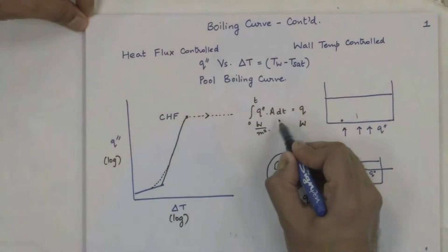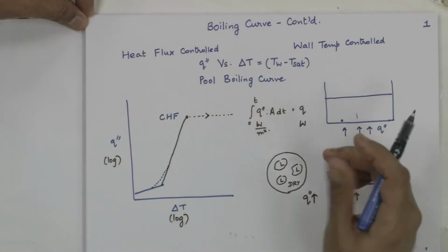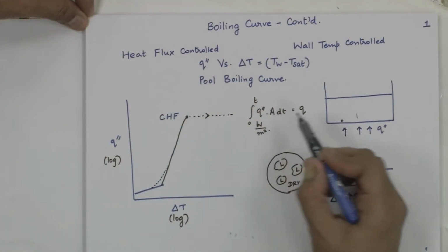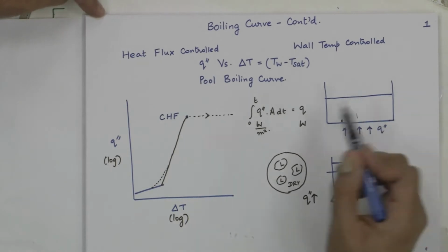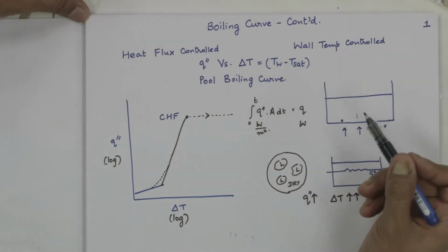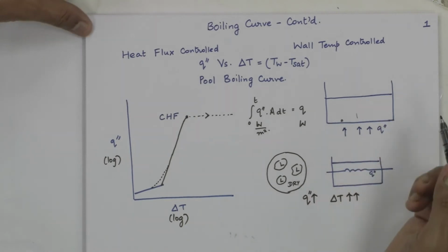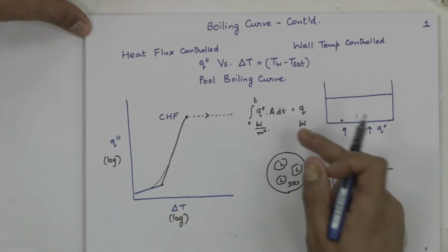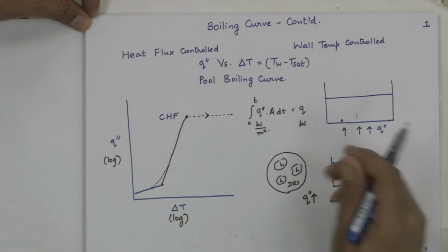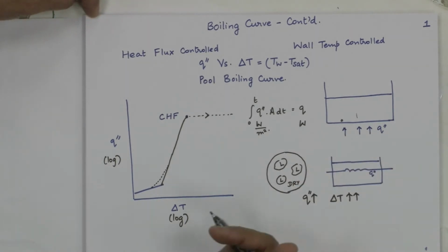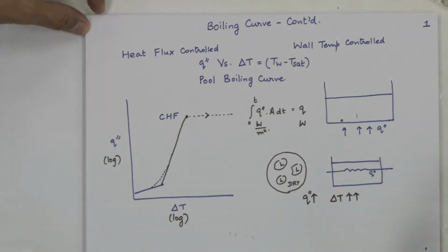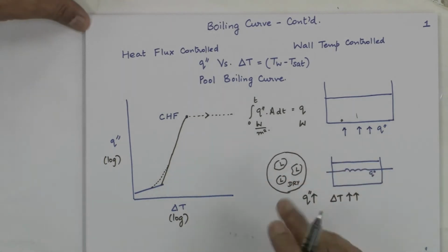This situation could have happened at a lower heat flux with a greater amount of time. So, if the gas was on a medium flame and you were talking on the phone for 2 hours versus if the gas was on high flame and talking for 1 hour, you could get the same effect. So, the heat flux alone is not a representation, the time also comes into play. Unfortunately, the terminology is such that critical heat flux is what is referred to by this situation.